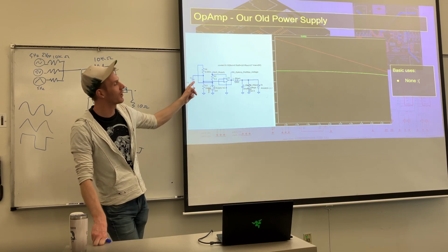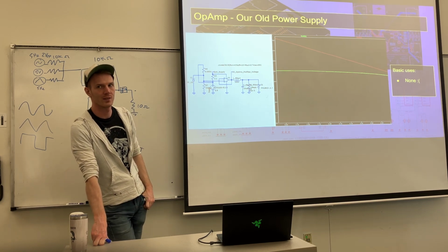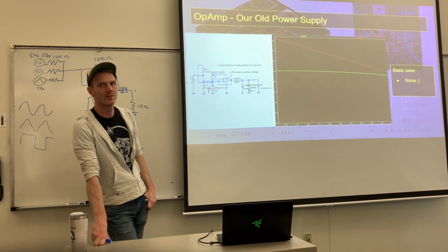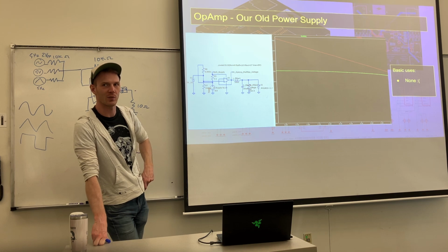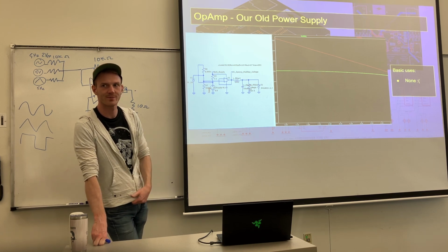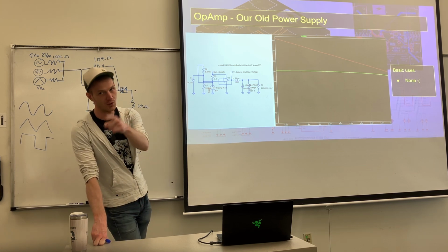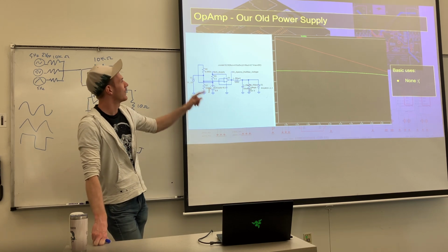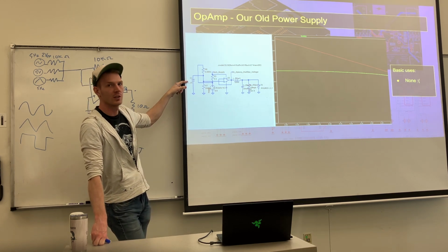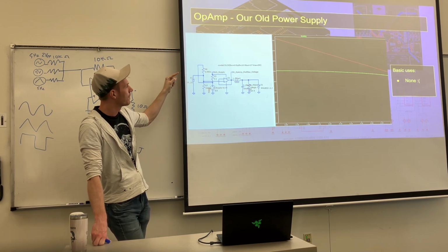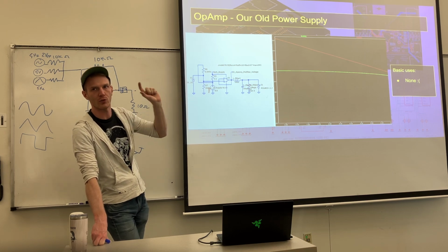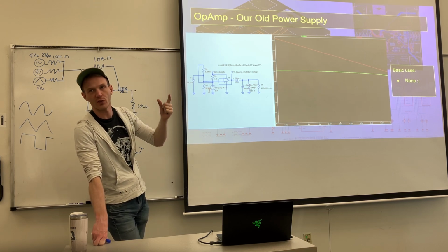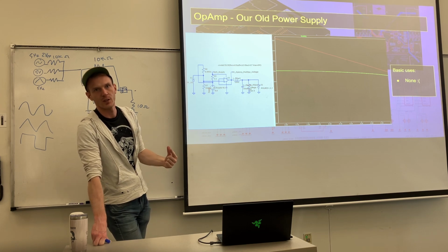Why is it pointing the wrong direction? Does anybody remember that? Oh, it's the inverse one. It flows the opposite direction. And why does it go the opposite way? There's a very specific purpose for it. You want to make sure you get 5 volts. The voltage drop across a resistor will vary with current. Zener diodes, if you recall, are very useful because they will always drop the same voltage regardless of the current, until you explode it.